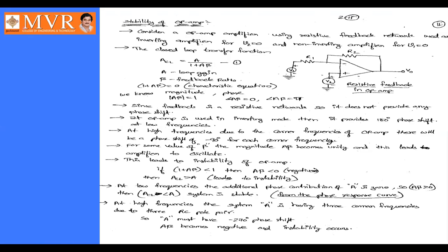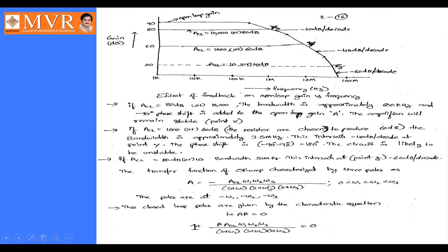Here we are considering the op amp is going to operate in inverting mode. So for that reason the gain is going to become A is equal to, here the negative symbol is due to we are going to use the operational amplifier as an inverting amplifier. So we are giving input to the inverting input of the operational amplifier, then the gain will be negative. Here you can see the negative symbol indicates that there will be phase shift between input and output.